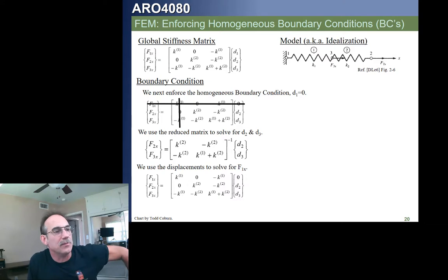And if you do that, you can plug in your external forces. They may have a value, they may be 0, and your global stiffness matrix, once you've constructed that correctly, and solve for the displacements, okay? Once we have the displacements, we then plug those displacements back in. We're going to go back to that original equation, which you see down here, and we're going to plug those in. Let's take a look at this.